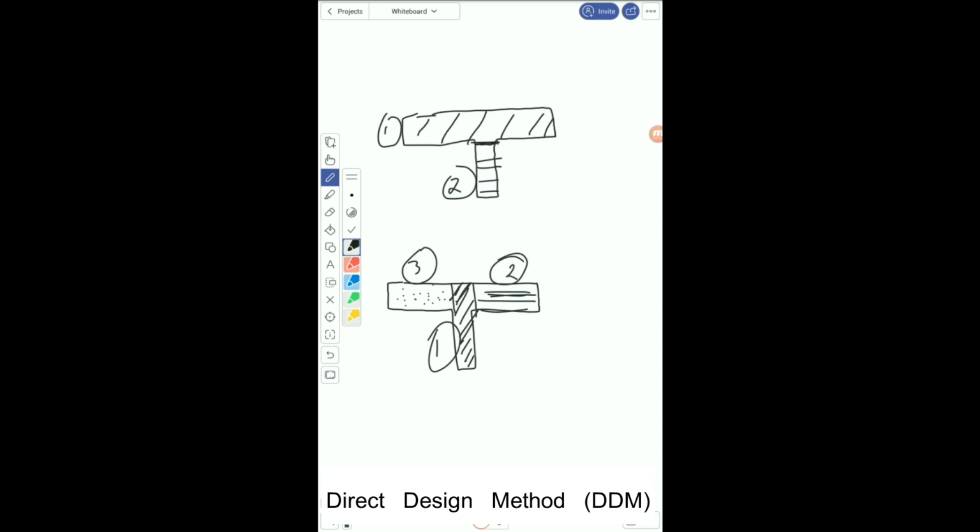So I'm going to apply the formula which I showed you earlier to these rectangular components, and I'm going to see which one of the two options will give the highest value of C. The highest value of C will be considered as the torsional constant for this T-beam.